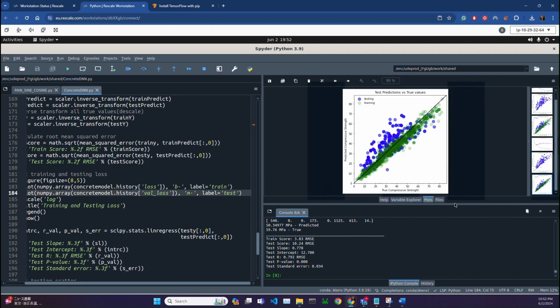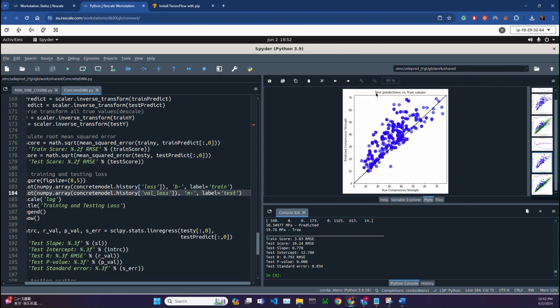Here I have a few more plots. This just simply shows true compressive strength against predicted one from the model. Values should be lying on the diagonal. You can see here as well where the training dataset is. It's actually very dense, around, let's say, 10 to 50 megapascal.